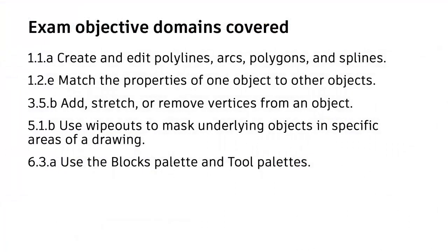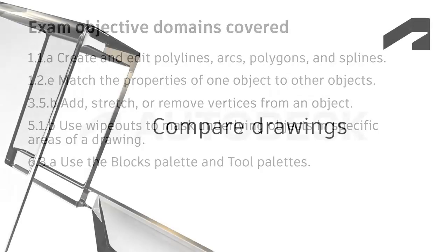In this lesson, we used wipeouts to mask some elements in our drawing to see how changes would appear. The Wipeout tool is useful when you want to explore different options without having to delete or modify existing elements in your drawing.